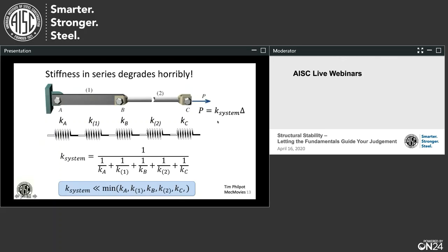Now, contributing to this stiffness are each one of the 3 connections and the longitudinal straightening of each one of the 2 members there. So in total, we could think of this really as 5 springs in series. So these members are in series, and if you wanted to compute the system stiffness, you'd have that sort of big gnarly equation down at the bottom.